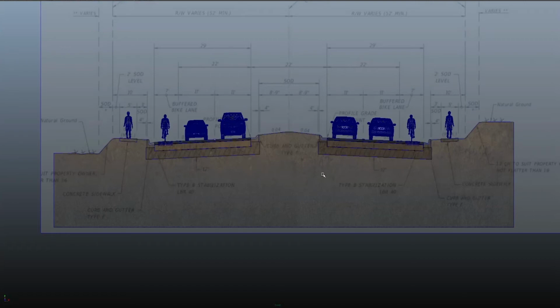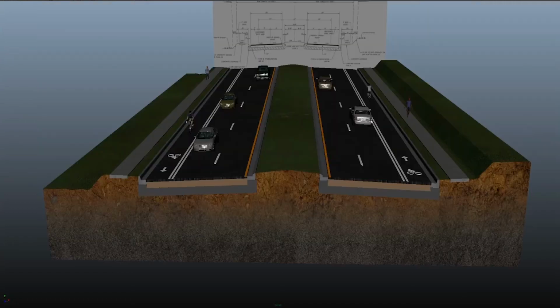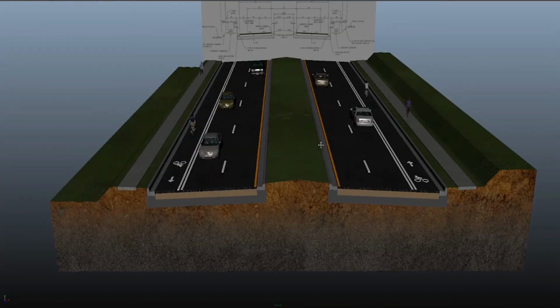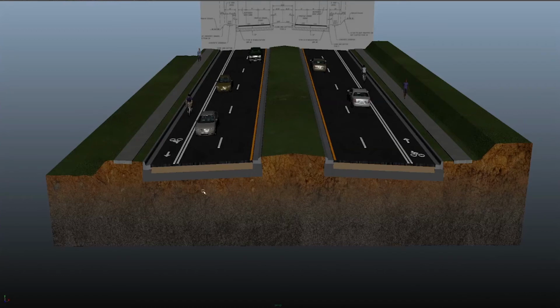3D file versus doing it in Photoshop or another image editing program. Because this is in 3D, there is a perspective that's going to be seen. If you do it in Photoshop, you have to go through a lot of extra steps to try to make that text look like it's somewhat 3D and matches the focal length of the rendering. And the need to use a second program to finish your 3D typical is something we always try to avoid. We want this to come right out of our 3D program done. It's so much easier to adjust and create text and the dimension lines this way.